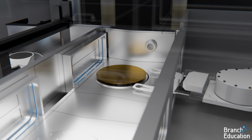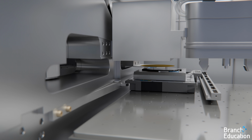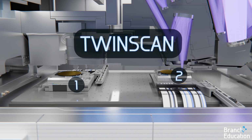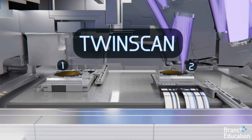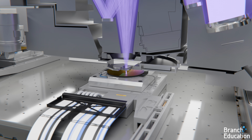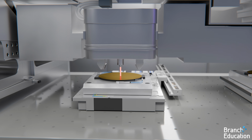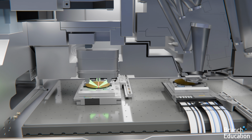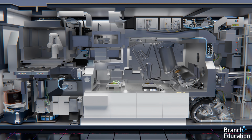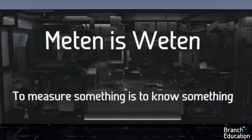Next, the back doors of the load lock open up, and a different robotic arm carries the wafer to one of the wafer stages. This system is called a twin scan because there are two complete wafer stages that concurrently move two wafers around. The key idea is that while one wafer is actively being patterned, a second wafer is being loaded onto the wafer stage and measured under an alignment sensor. Nanometer level accuracy is crucial with these machines, and one key philosophy of ASML is meten is weten, which is Dutch for to measure something is to know something.